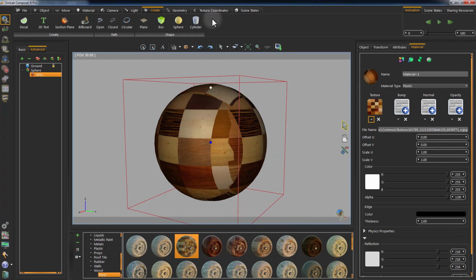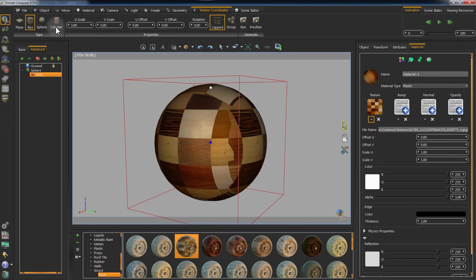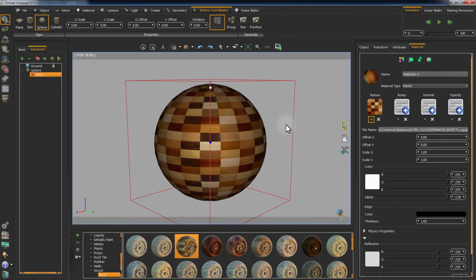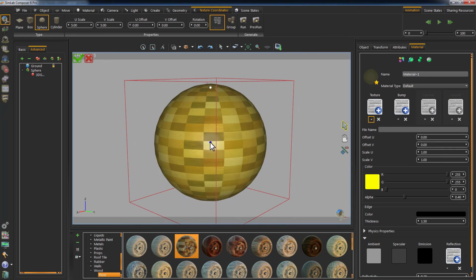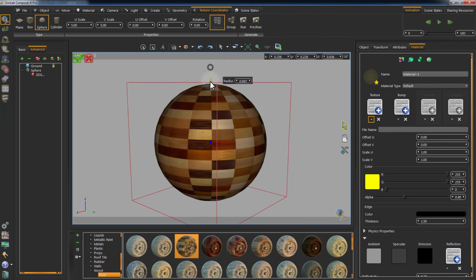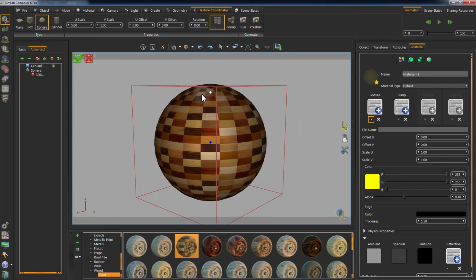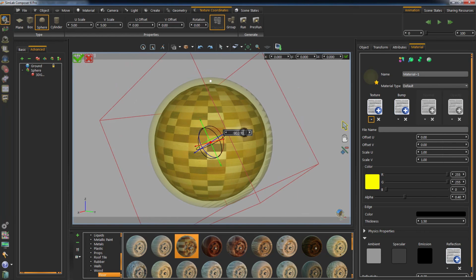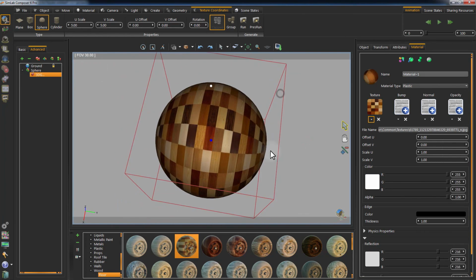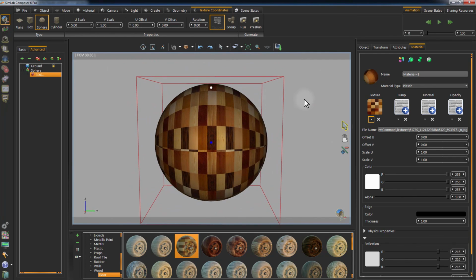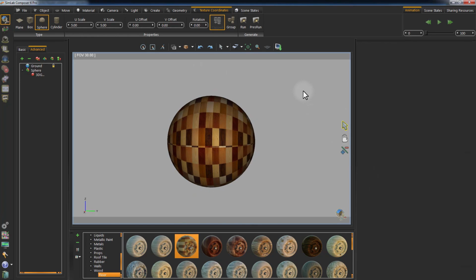Go to the Texture Coordinates tab and select Sphere and click Run. With a simple click, we have created texture coordinates for the sphere. The same tools we applied in the box generation apply to the sphere, as well as the plane and cylinder geometry. The texture coordinates generation in SimLab Composer is simple to use and effective. It will save you time by allowing you to enhance the texture display without the need to revert to the 3D design software.